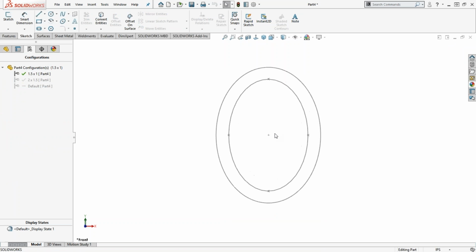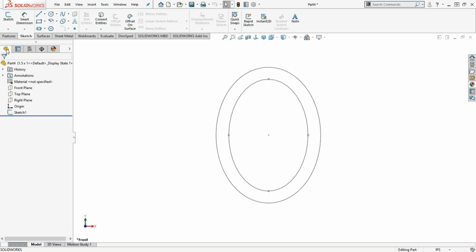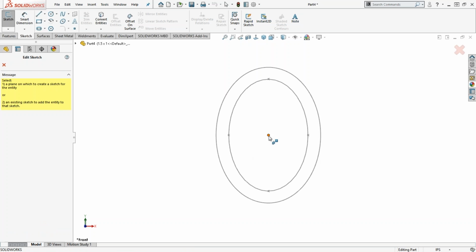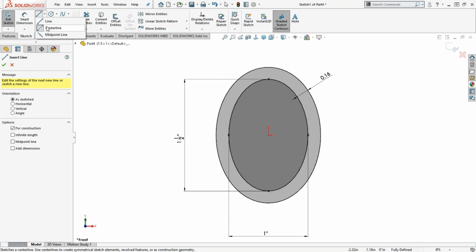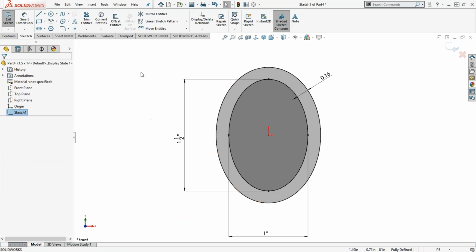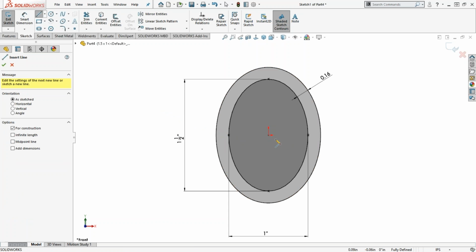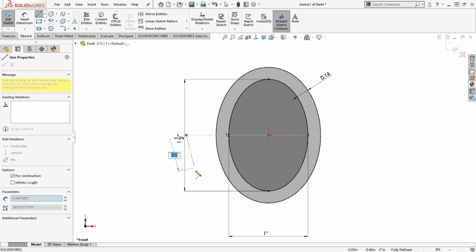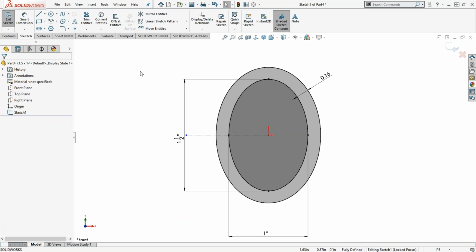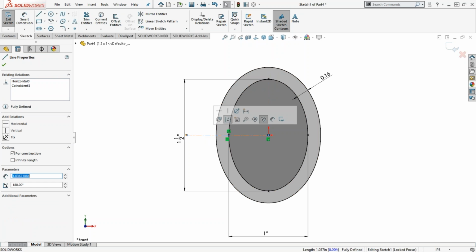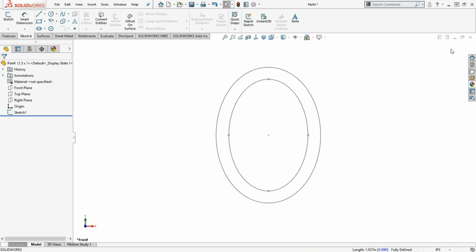So I've basically defined all the sketch geometry I need for this profile. It's pretty simple in this case. You can add additional sketch geometry like center lines. They can help SOLIDWORKS decide how to orient a weldment profile when you apply them. These aren't necessary, but sometimes they can help when you're doing more complex weldment profiles. So just food for thought there. I'm going to go ahead and delete this just so I don't have any unexpected behavior.